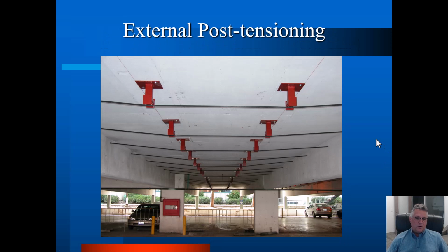One of my favorite parts of post-tensioning is external post-tensioning used to retrofit sick old buildings that have had corrosion or something wrong with them, or to just increase their load capacity. In this particular case, this was a Newport Beach project where, because it was close to the beach and it was back in the days, believe it or not, they only wrapped the strands in paper, greased paper, and the grease just disintegrated over time, and so did the paper. But then so did the post-tensioning.